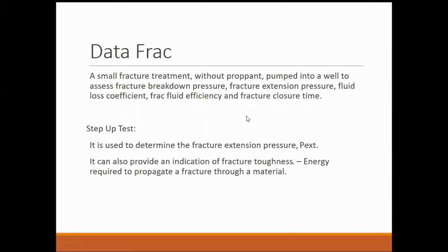It is done without proppant, and just the frac fluid is pumped in the reservoir to assess a few parameters, which are breakdown pressure, at what pressure the formation is breaking down; fracture extension pressure, at what pressure are we able to extend the created fracture further into the reservoir; and fluid loss coefficient, at what rate is the fluid getting lost into the matrix. Okay, so you have to pump at a rate faster than that, so that your fracture can always have fluid inside it.